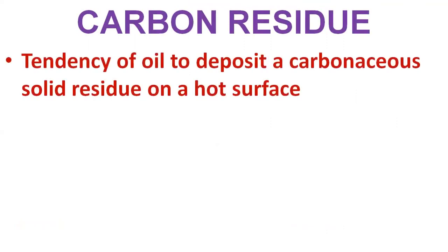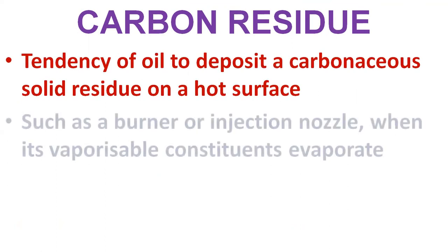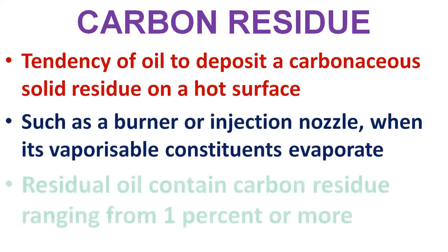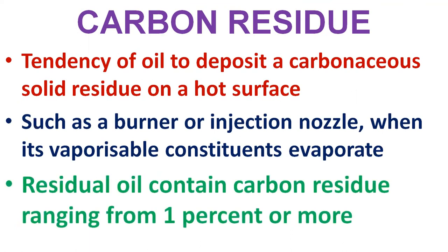Then there is the carbon residue, which indicates the tendency of oil to deposit a carbonaceous solid residue on a hot surface, such as a burner or injection nozzle. When its vaporizable constituents evaporate, residual oil contains carbon residue ranging from 1% or more.